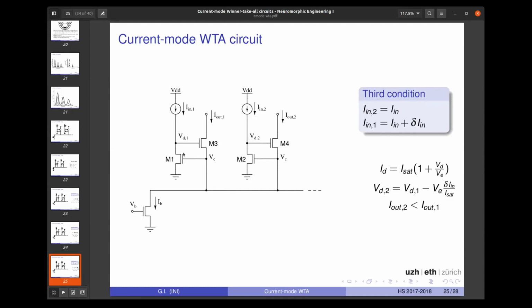If we smooth input currents, we can have winner-take-all circuits that act as selective amplifiers for a population of inputs, a bump of inputs, and not a single pixel input. If there are no questions up to now, I'll go on to the next slides to show you how to extend this to this more biologically similar circuit where you can have bumps coming in.